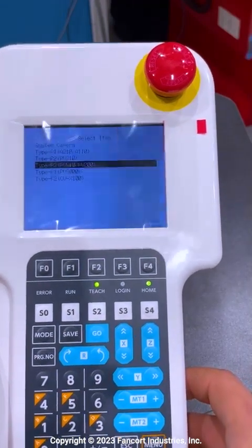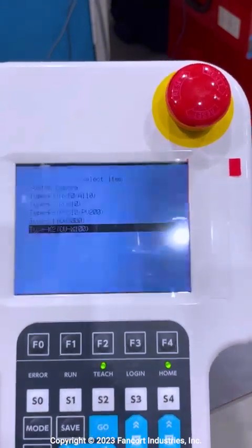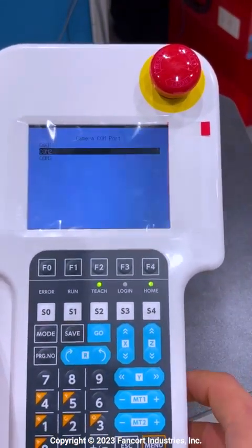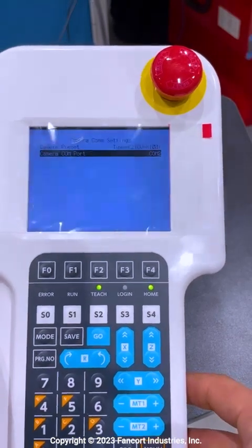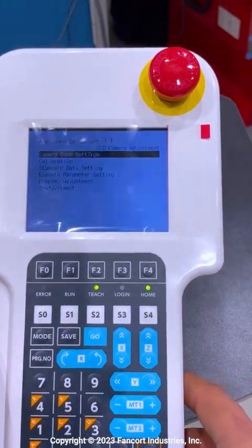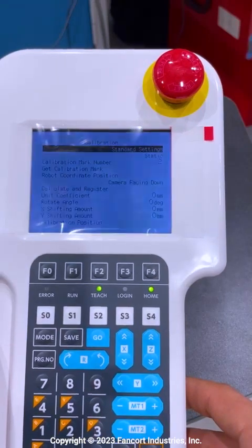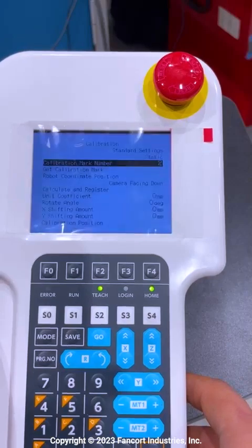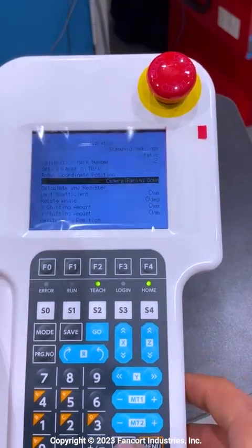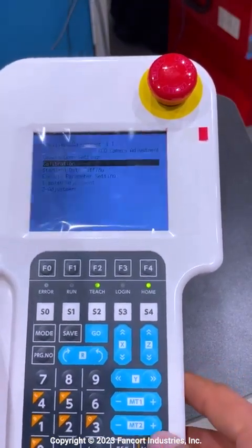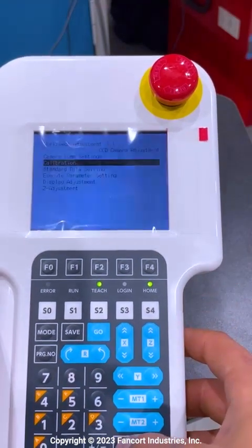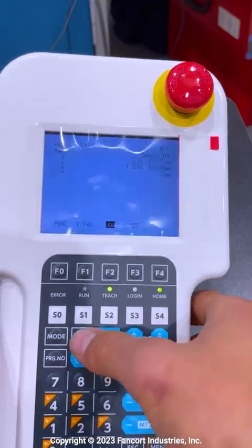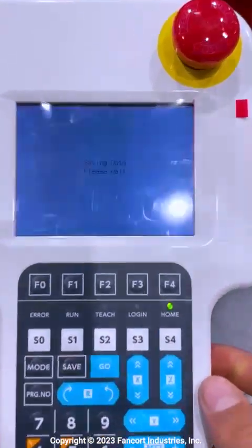and we're going to select the last one because that's the type of camera that's on, and we're going to make sure that it's in COM 2, COM port 2, good, and then we're going to escape. We're then going to go into calibration. We're going to make sure that we're static and calibration mark 2, and we got the camera facing down. Escape. And then we're going to go escape, escape, escape, and we're going to hit save right there. And it's going to save.